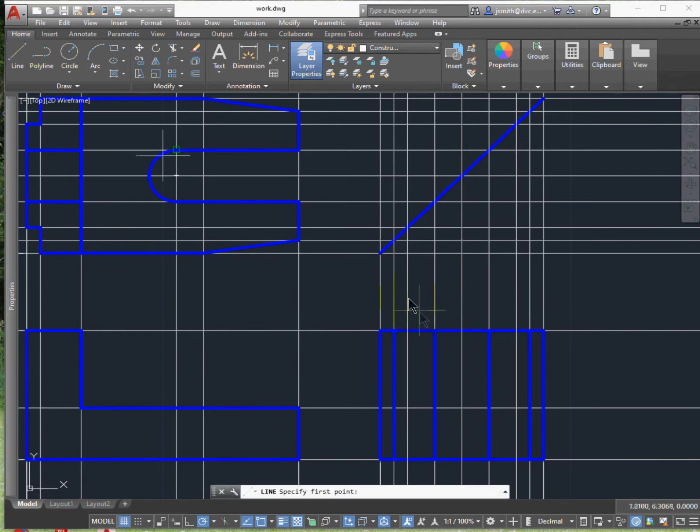And so the way that I'm going to do this, I'm going to build a line, and this line is at 30 degrees of an angle. So I'm just going to go ahead and build a horizontal line, and then type in rotate, and I'll select the point, which is at the top of the part, the corner, and I'll just go ahead and type in 30 degrees. So when you type in minus, it goes actually clockwise. When you type in positive integer, it'll go in counterclockwise. And so that's going to be my 30 degrees.